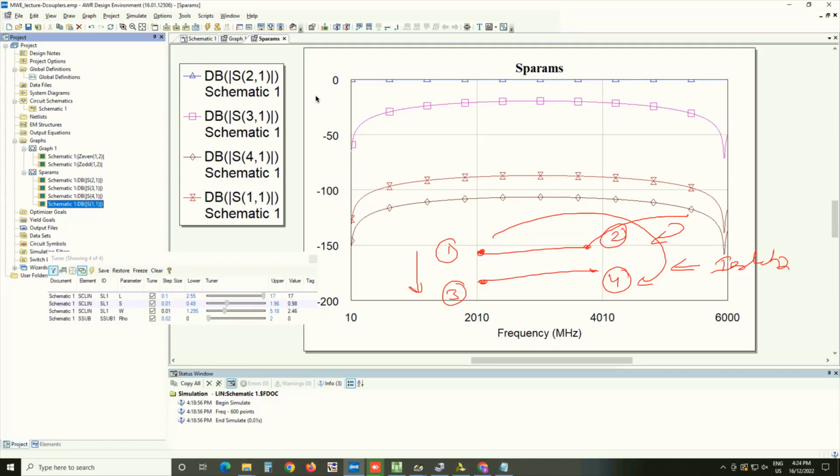And that is going to interfere with the reflected signal you have sampled. And the same thing on the other side, that the reflected power which is coming from port 2 and should only have gone to port 4 will interfere with your incident power sampling at port 1 because it will come out of port 3.